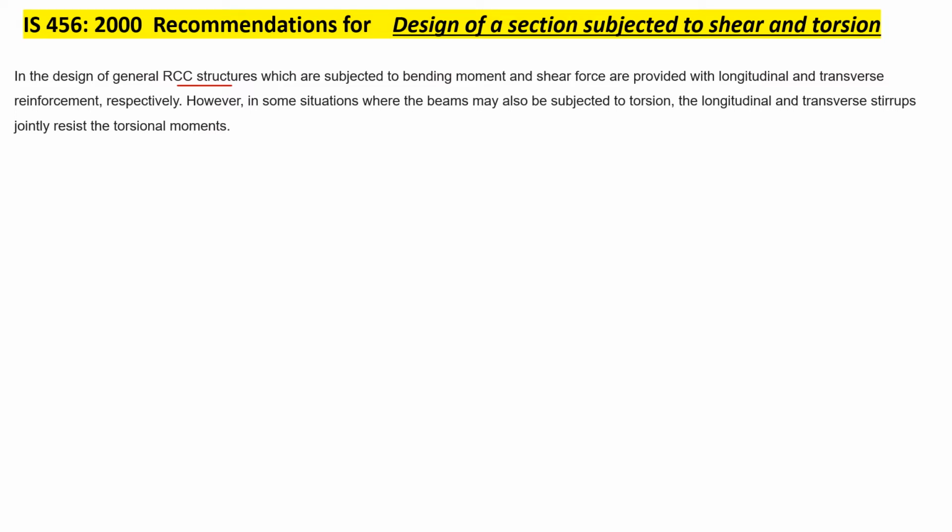However, in some situations the beams may be subjected to torsion, so then we have to design the longitudinal as well as transverse reinforcement. So longitudinal steel and transverse reinforcement jointly will resist the torsional movement.